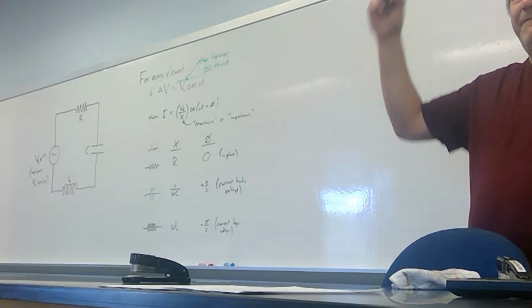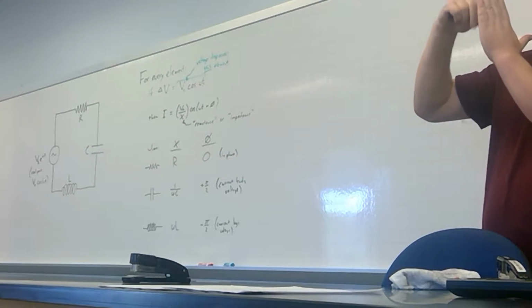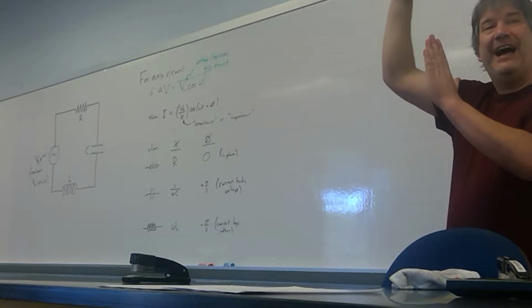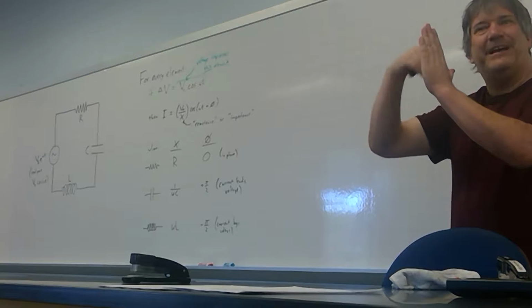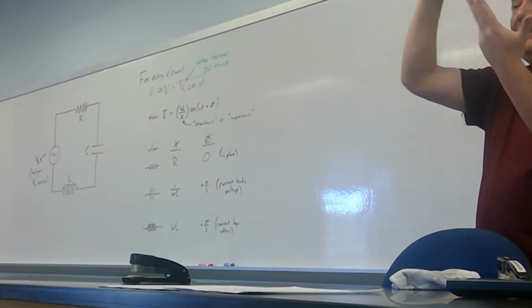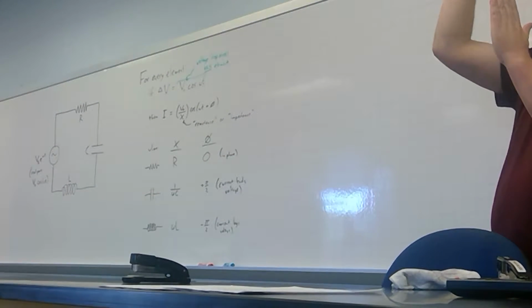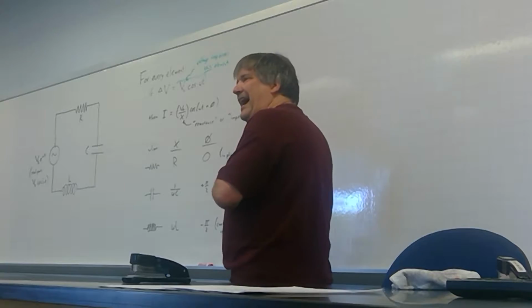I put a really fast signal through a capacitor. So I run current back and forth through the capacitor really fast. Does it build up very much voltage across it? No, because there's no time. Every time it starts charging one plate, the current switches around and discharges that plate and charges the other one. So if I run even a fairly high amplitude current back and forth through a capacitor, if I'm running it fast enough, the voltage never builds up to very high amounts.